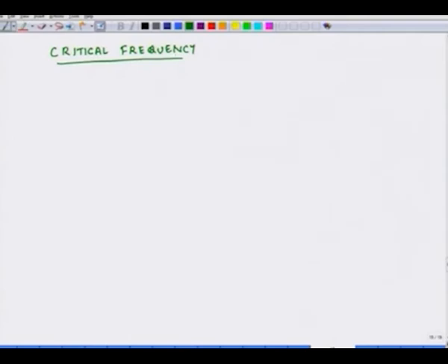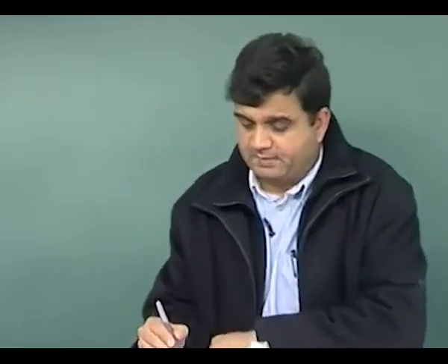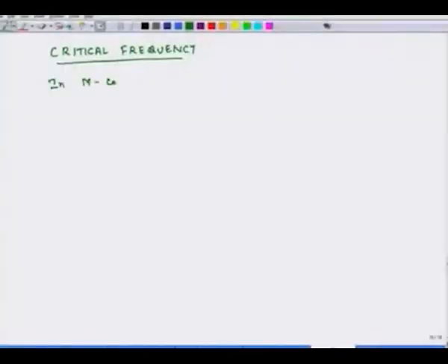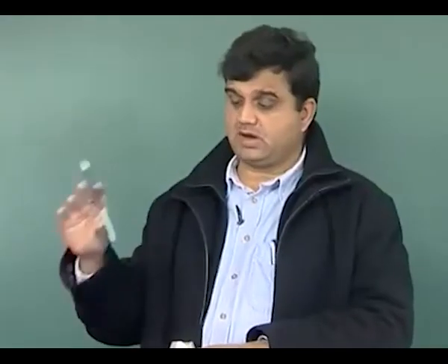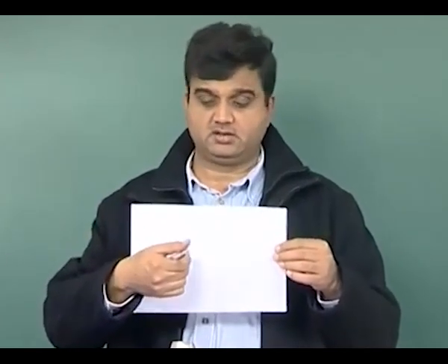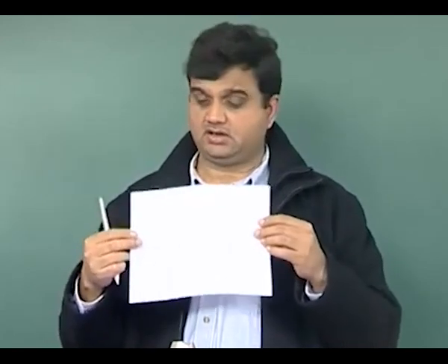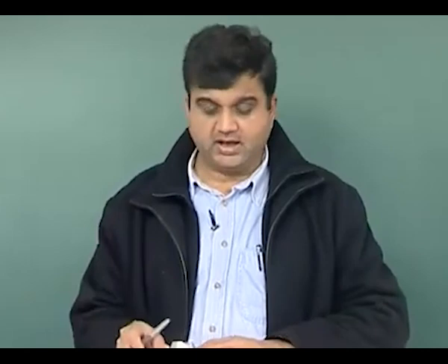So, what happens is that in the mass controlled region, as my frequency goes up, as omega goes up, the wavelength of the sound goes down; the wavelength starts shrinking. Also, these sounds try to excite some bending waves in the plate or the wall we are talking about. So, if I have a plate and it is being hit by sound, there may be some bending waves in the plate.